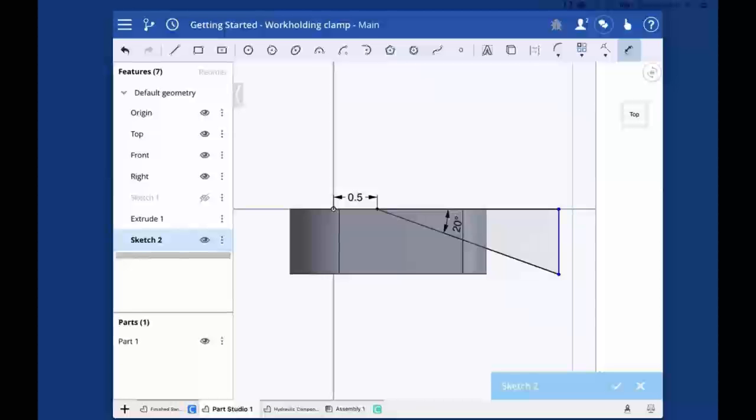One of the easiest is with the use command. So you'll see the use command in the toolbar right there, and it allows us to take a silhouette like this and convert it into sketch geometry. You'll see I used the precision selector there, moved over the radius, and then let go, and it adds a line right at the silhouette of that arc.